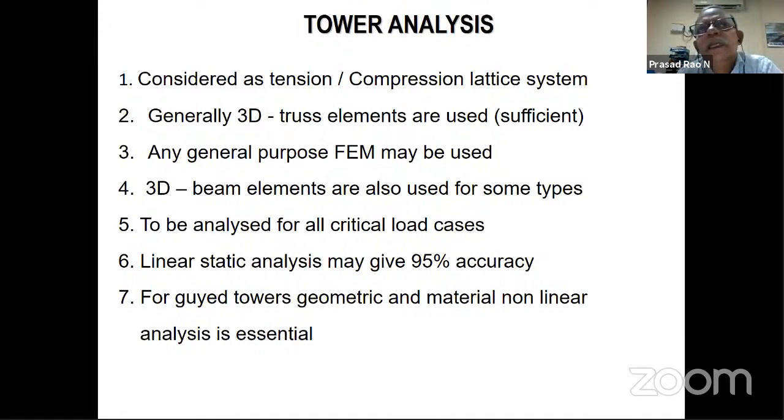You can use a beam element. Suppose you want to know the stresses across the cross section of an angle section, we need to go for a plate element, plate shell elements. I think plate and plate shell elements are known to everybody.